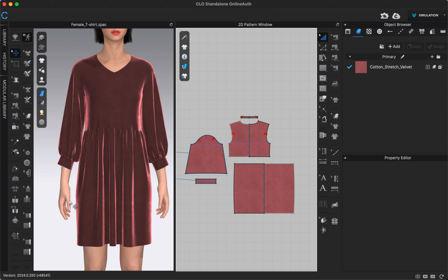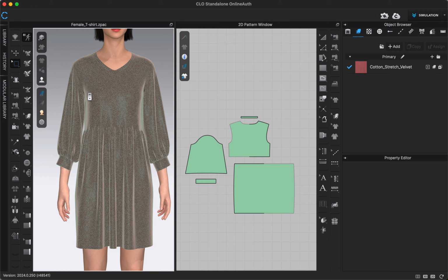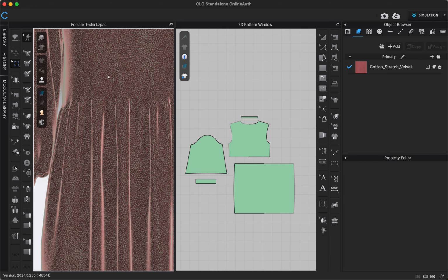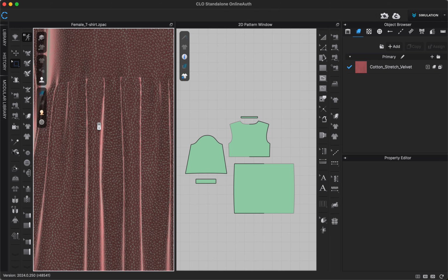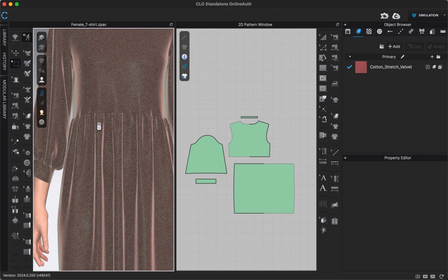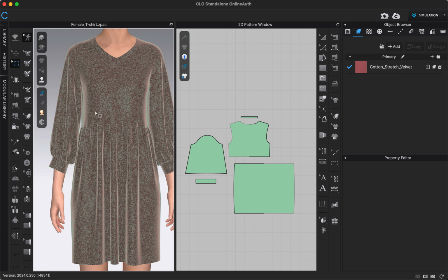And now I'm going to switch back into the mesh mode just so we can see what the particle distance looks like now. And you'll see that the particle distance and mesh of our garment is much smaller now. So now the frame that our fabric is draped over has much less sharp corners, it's much smoother, and that's basically what switching into high resolution mode does.